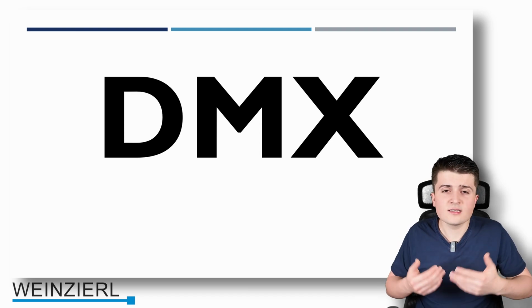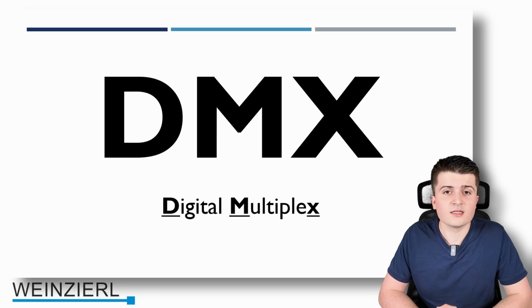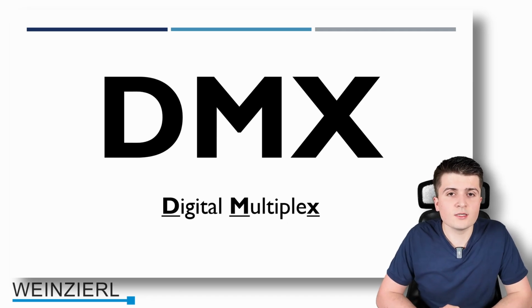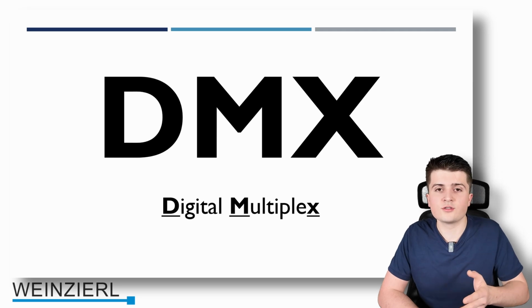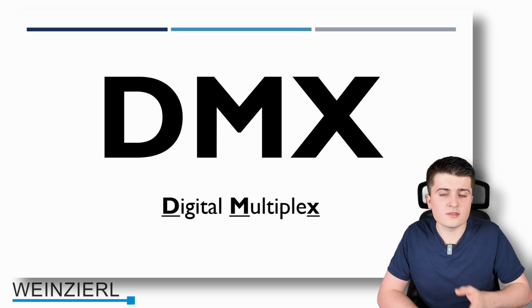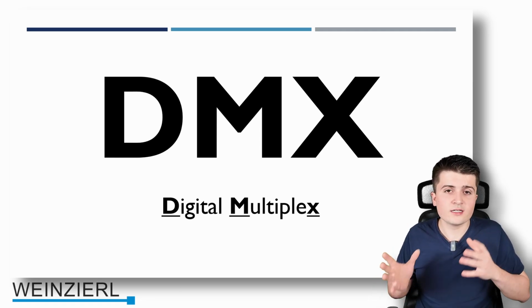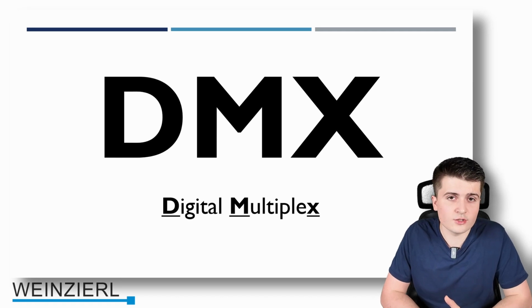First of all, DMX stands for Digital Multiplex. But what is DMX? Well, DMX is a control standard used for lighting control, effects, etc. So DMX is commonly used within the event industry in the stage technology and is used there to control the stage lighting, effects, etc. And because of that, you have a wide range of different lights that you can use, and therefore it's really interesting to use DMX inside your building. And this is where the Weinzierl KNX DMX Gateway comes into place.